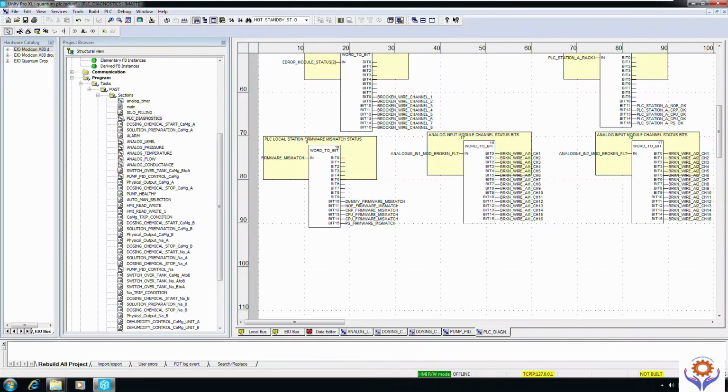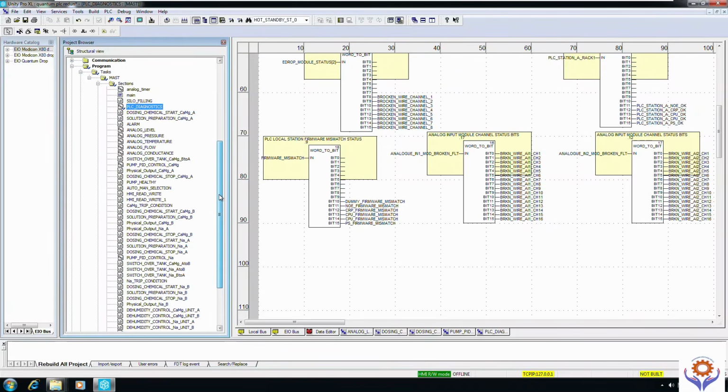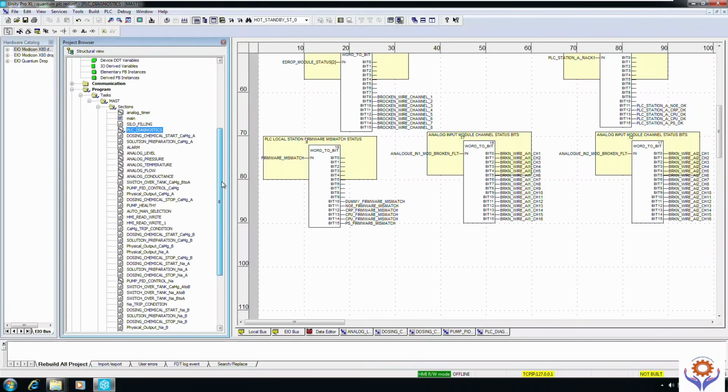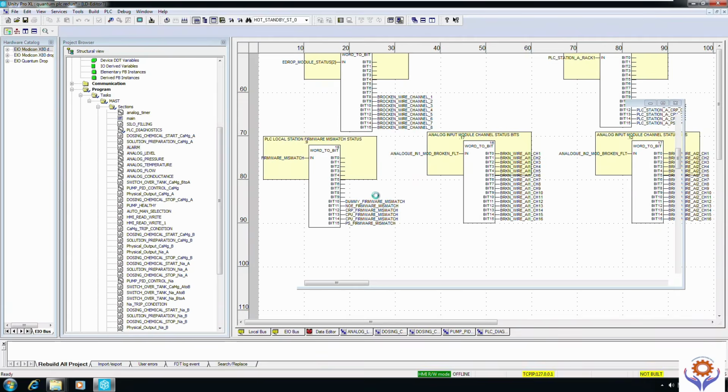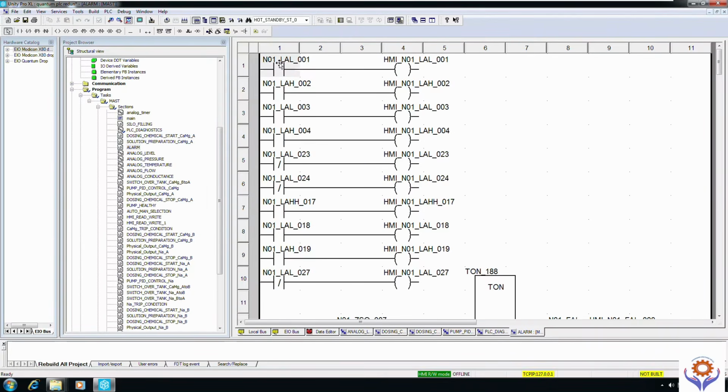And also you can check the firmware version of each CPU, CRA, power supply module, everything there. And also for each analog input, digital input, analog output and digital output. For everything you can make the logic, like you can take the block and utilize it with the system words, and this will be configured in the SCADA system. This will be very useful for beginners or engineers who need to show every signal in the PLC. You can use this type of system words.